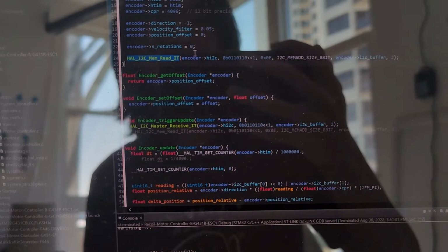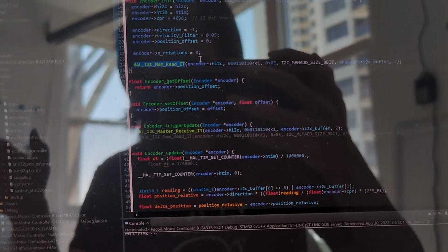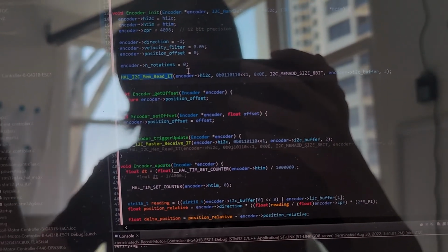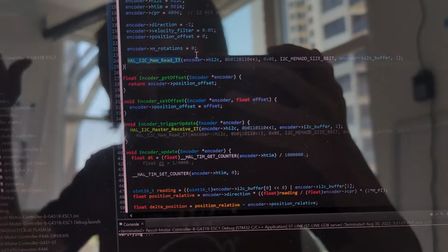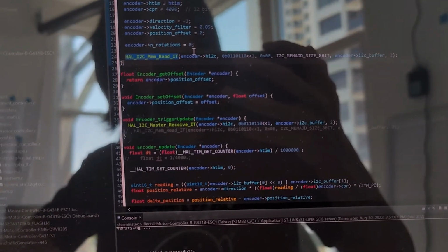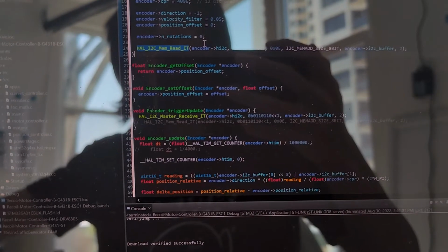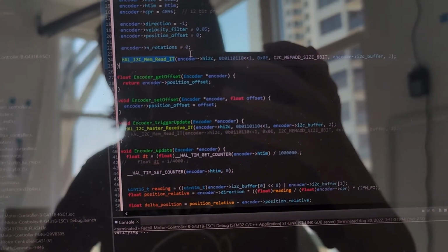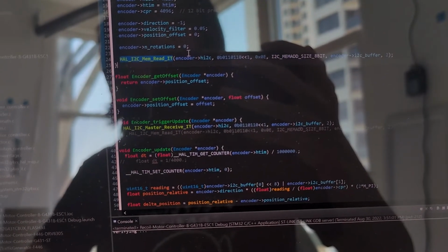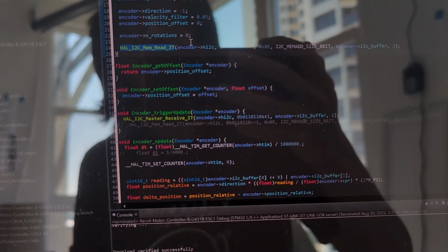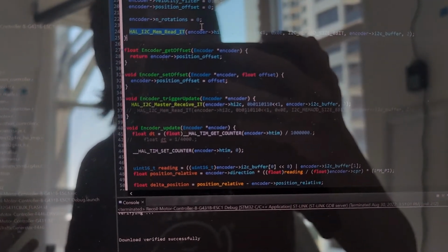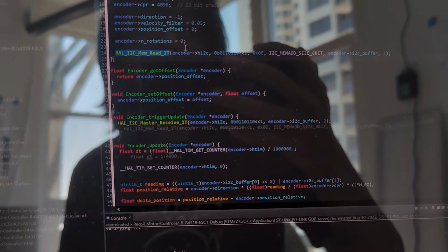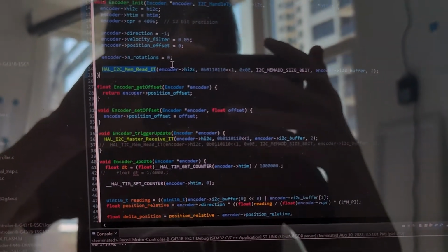That's confusing terminologies. Firstly we need to transmit the entire write and read sequence, but afterwards we can just issue the read commands, and it will automatically transmit whatever address we previously requested and return the up-to-date data. So that's a thing to change.